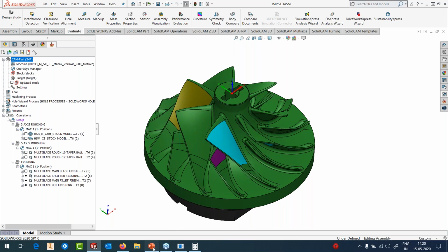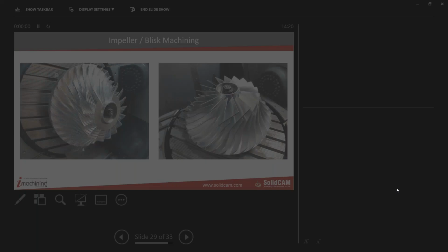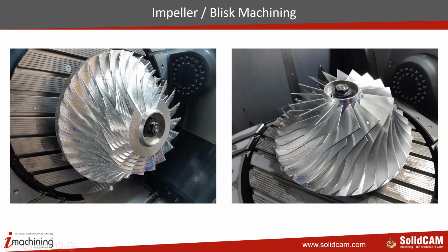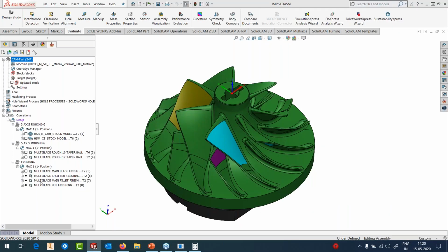Now, the part that you saw here, this did not have any buckling. This particular part, the upper thickness is about 1.6 millimeters, and it goes down to about 2.5 millimeters. That's the thickness that we have. And here also we did it in stages. We allowed it to age. In fact, we roughed it completely for one full day, and we left it overnight to age, came in the morning and then just finished the part. Many people won't agree, but there are other ways of doing it.